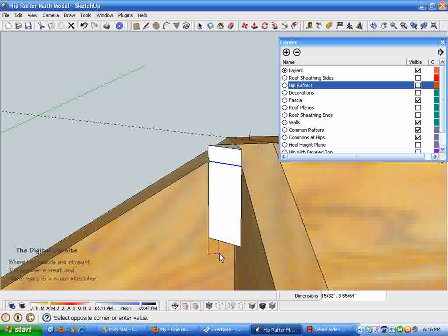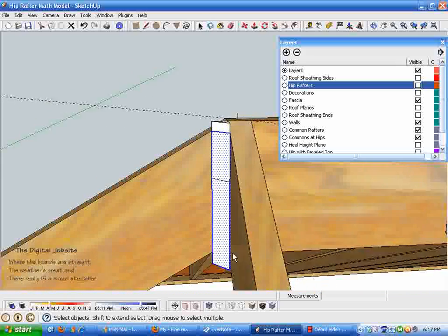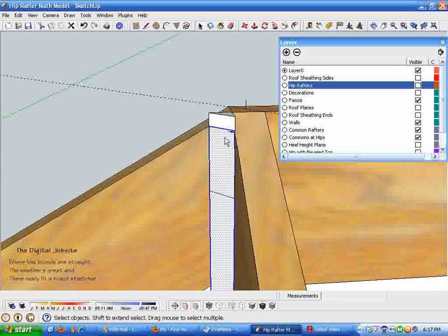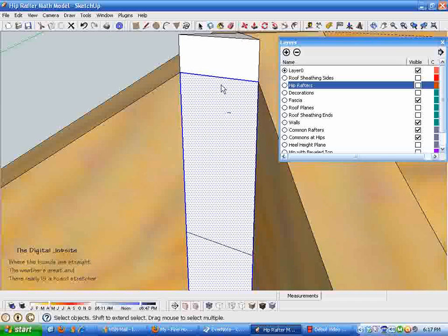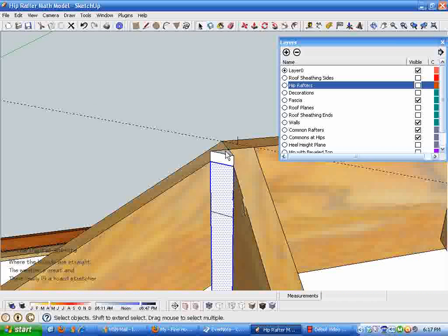It's trying to do all sorts of things, but I want to end up with a rectangle that's the cross section of our hip rafter, which in this case is going to be 9.25 inches, comma 1.5. So that gives us a rectangle. It's a cross section of a 2x10 with the top of it right at our hinge point. Hopefully it'll make sense as I develop the process.